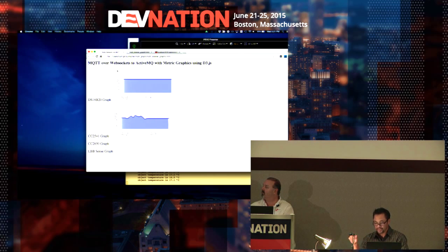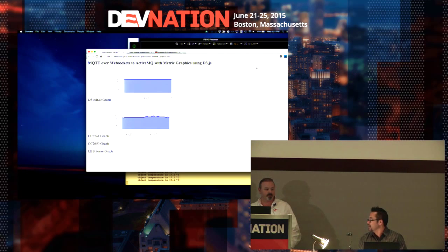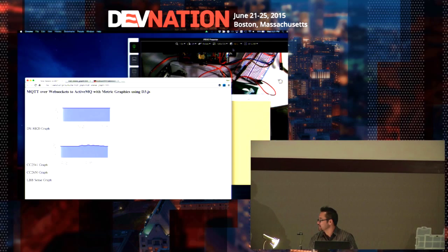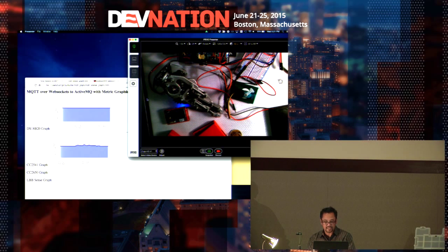But so it's doing real-time temperature sensing right now and pushing that out to the broker, right? So it's Bluetooth to Wi-Fi to this box where the broker is running, MQTT output router. And I'm using the MQTT NPM, which is basically a great little tool for doing all sorts of craziness. So I can just let that run in the background there. But for instance, I can send MQTT messages. Kind of come back up here where I have my other window.